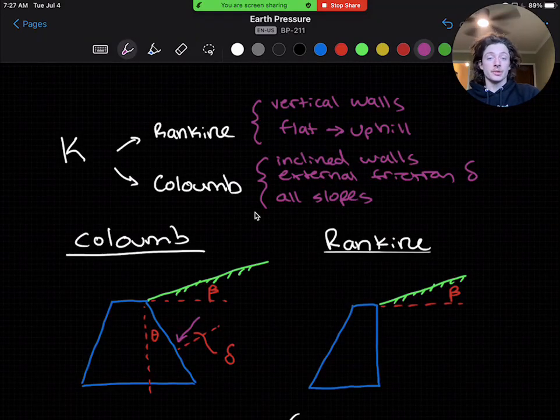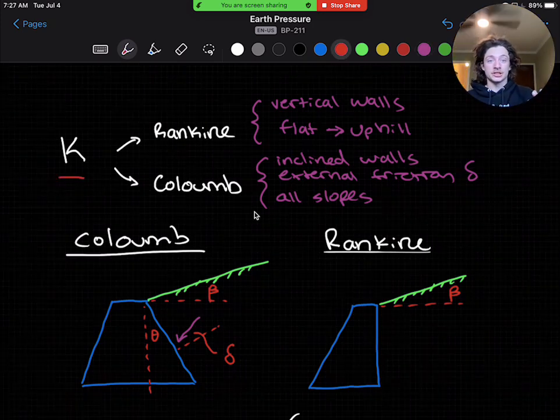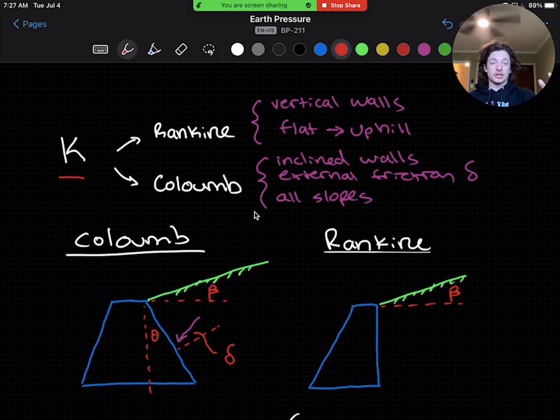Like I mentioned in the previous video, and just to reiterate, soil forms a triangular distribution of pressure, generally, so non-cohesive soil. And the deeper we go, the greater the vertical pressure from the soil weight above. You can think of this just like water, except the vertical pressure is converted to a horizontal pressure with the K coefficient, which is our coefficient here. Unlike water, which is a liquid, the horizontal pressure is assumed equal to the vertical pressure. The pressure is the same in all directions.